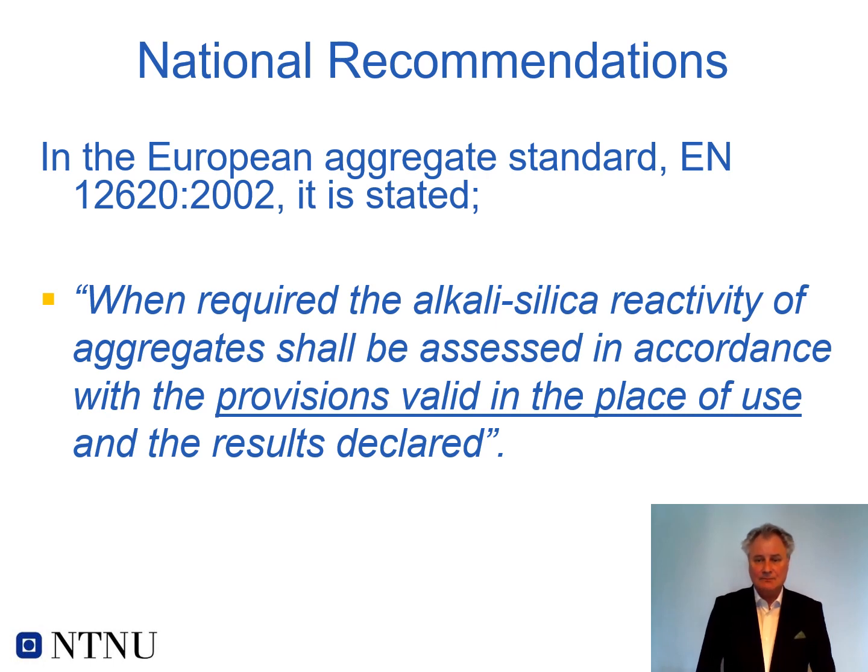When it comes to European standardization, it is a little bit tricky because we do have a lot of European test standards for aggregates and so on, but we don't have a European test standard for alkali aggregate reactivity. It says in the 2002 version of the aggregate standard 12620 that when required, the alkali silica reactivity of aggregates shall be assessed in accordance with the provisions valid in the place of use and the results declared.